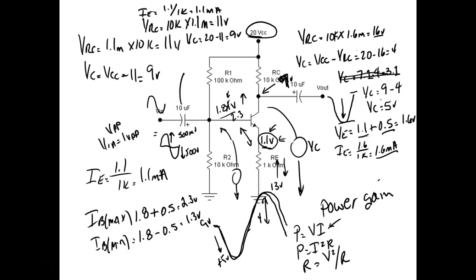So if this was my left channel on my stereo and it gave me 180 degrees, and I use the same amplifier on my right channel and both of them have 180 degree phase shift, then your speaker would be okay, right? If you ever looked at a stereo, your left and right channels are going to be mirror images of each other. So whatever we have down in this one is going to be what we have in that one.